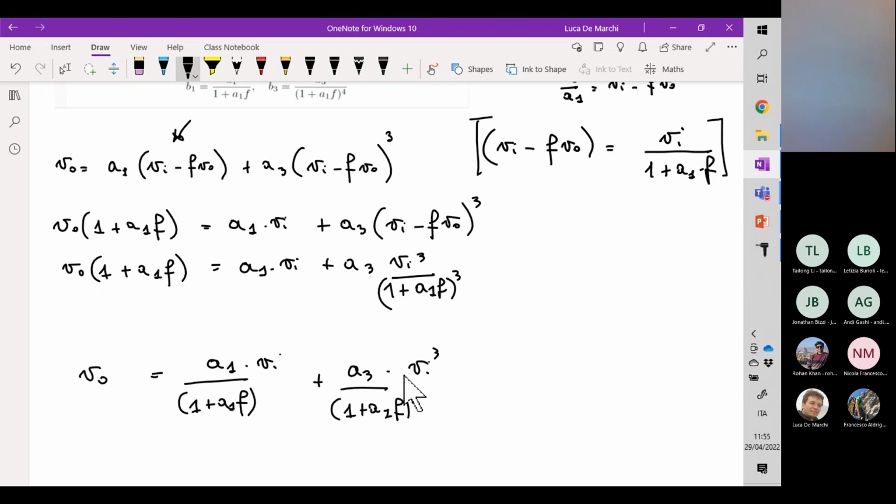In this specific case, A of j omega, as you see, is a single pole function. We have just a minus 90 degree phase loss in our system. And if we look at the phase at the omega 0 dB angular frequency, the phase is equal to minus 90 degrees. So if we perform this computation, the phase margin is equal to 90 degrees: 180 minus 90 degrees.